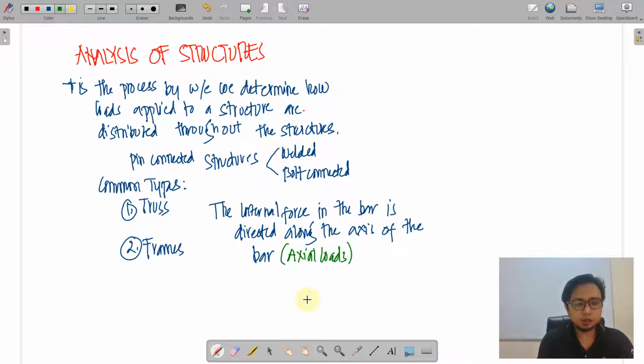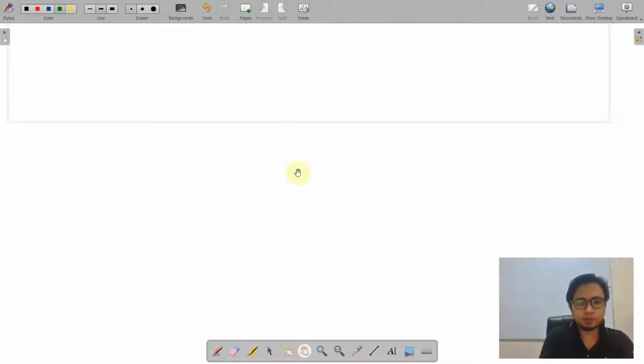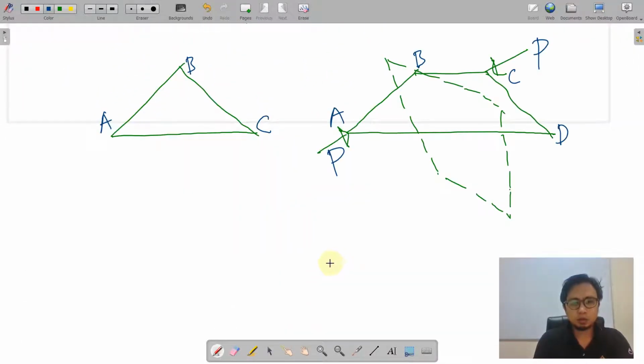So let me revisit you on the structure wherein there will be a rigid structure or a mechanism of structure that is unstable. We have two structural systems here. For the first, you can see on the left, it is rigid because it is supported by three force members. On your right, there are 4 pin connections on this system, so it will have a mechanism of instability.